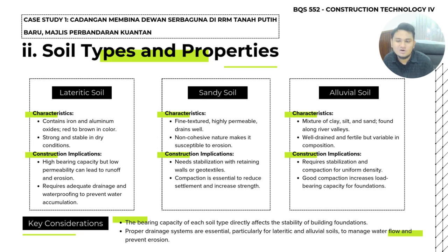The key consideration of soil types and properties for this case study is that the bearing capacity of each soil type directly affects the stability of building foundations. The proper drainage systems are essential, particularly for lateritic and alluvial soil, to manage water flow and prevent erosion.